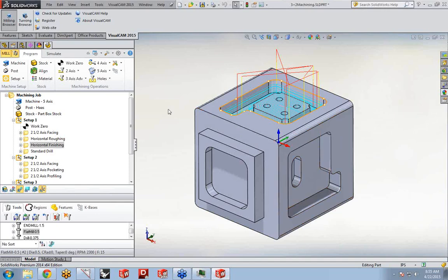One of the things you could do is take the CAD model into Rhino and export all of these machining operations, what you program, into a knowledge base. So the machining operations are interoperable between our different plugin products. You can save all of the machining operations to a knowledge base, and then import that knowledge base into your other VisualCAM system, VisualCAD Standalone or RhinoCAM, and use those operations to program the parts. So the machining operations in the tool library can be shared between our other plugin products.